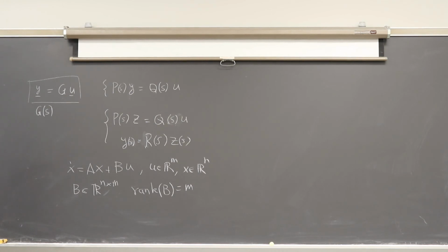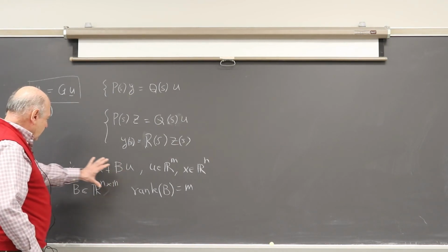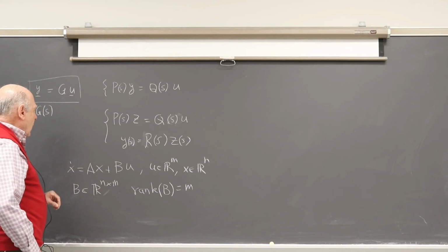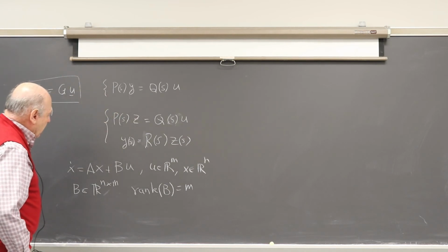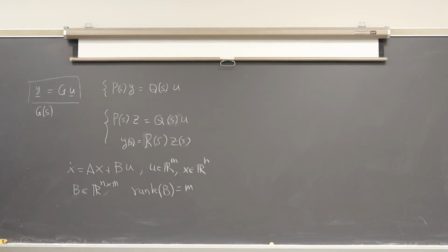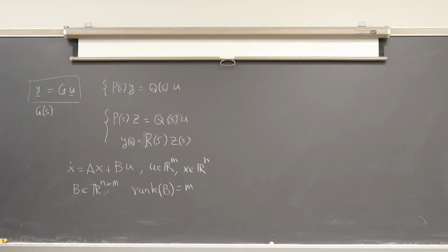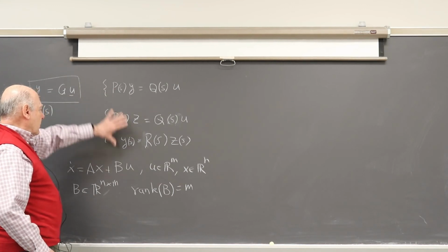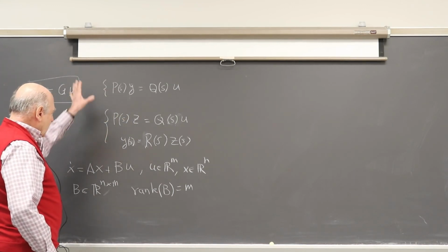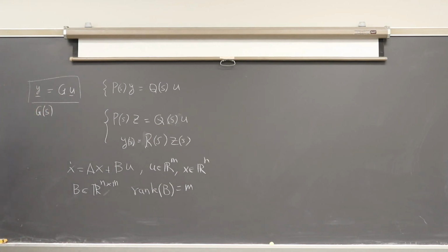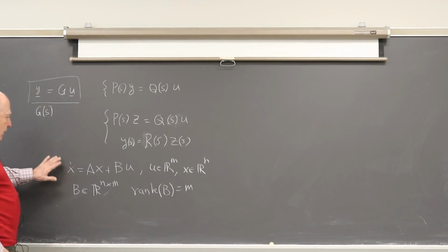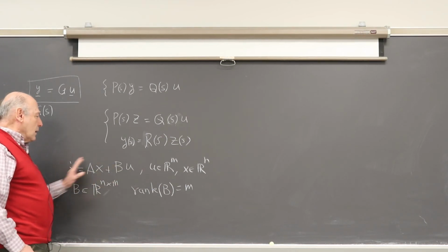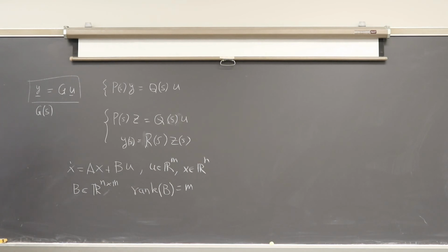So for this, the concept of flatness is very useful and very direct to apply. In these representations, the applications are somehow a little bit more difficult to encounter in practice. But of course, many systems can be represented by any of these three types of models, and it's only that this being more popular, you find many more examples as a direct linearization of nonlinear multi-input, multi-output systems.